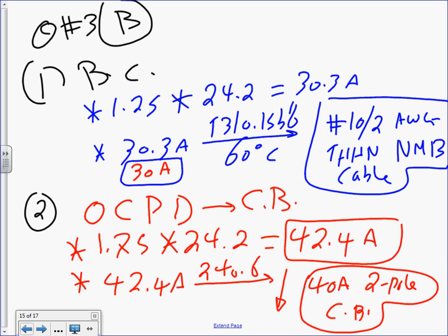Now I have an overcurrent protection device of 40 landing on the 30 amps. These are HVAC equipment and motors and so forth. That's okay in this case. Can I lower the 40 amps to 30 amps? Yeah. For circuit breakers, guys, you can go that when what you're sizing is the maximum.